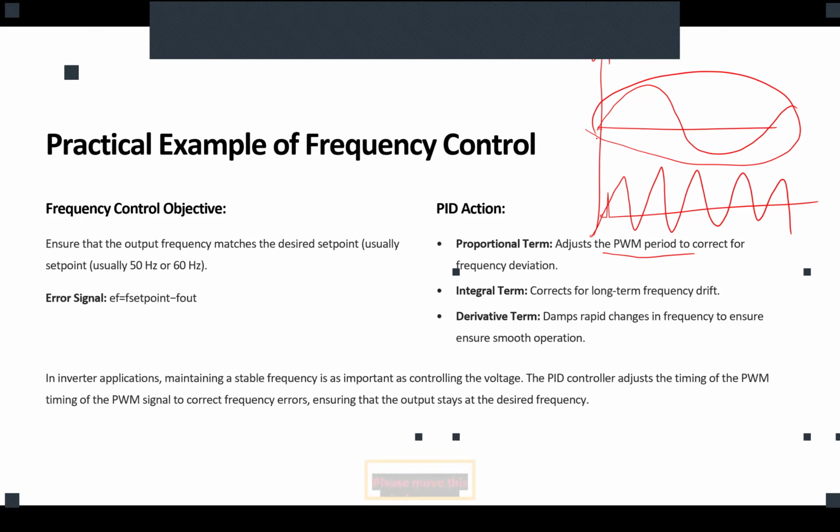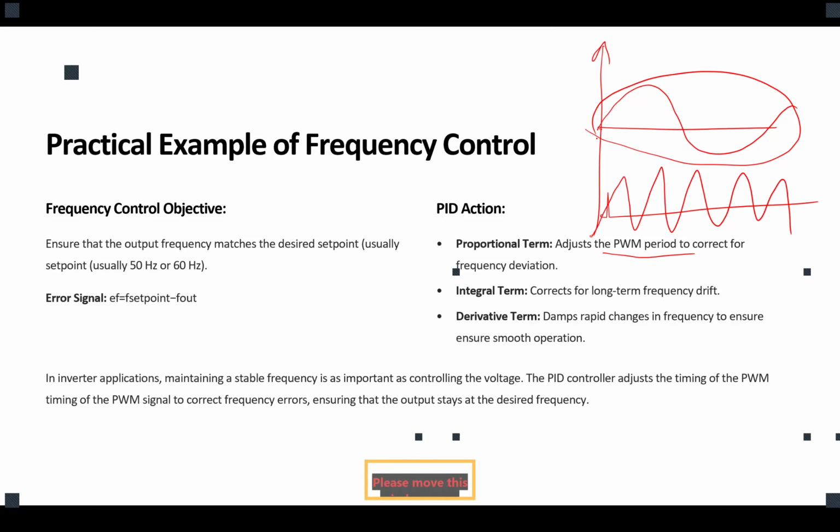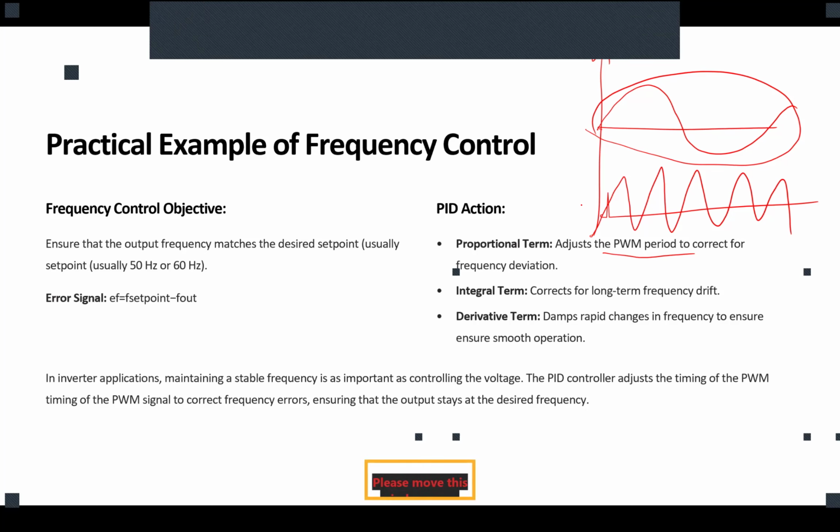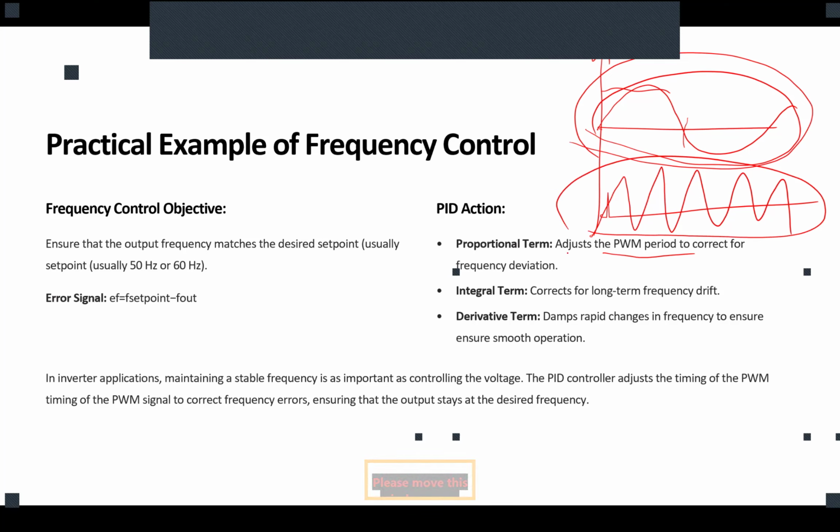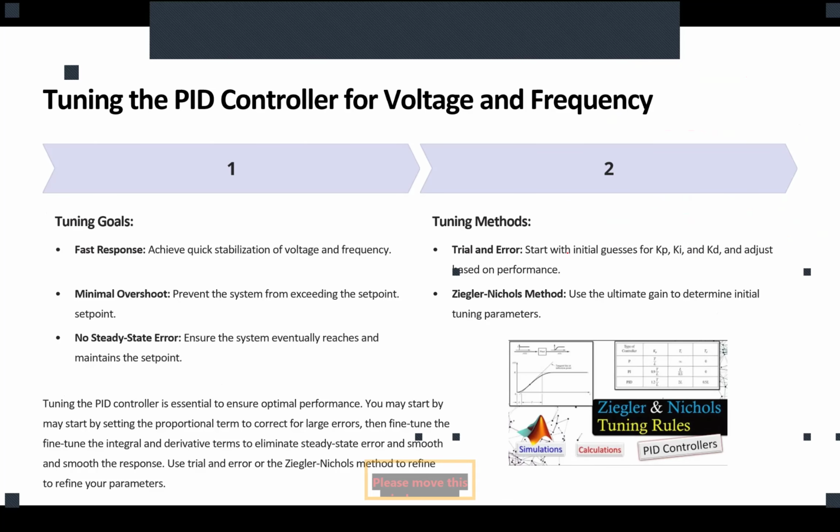Are we good? The reason that they don't use, that's a good point, the reason that they don't use the switching frequency for duty cycle control is because it's easier. For voltage, you control the amplitude. For frequency, you control frequency. So you have only one signal to play with. You know, a simpler control circuit. And you keep this solid. Make sense? Any questions? Now,